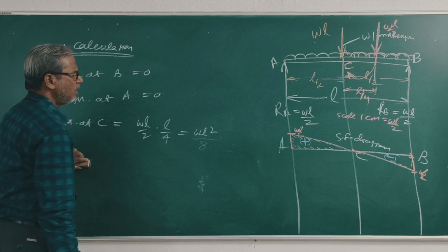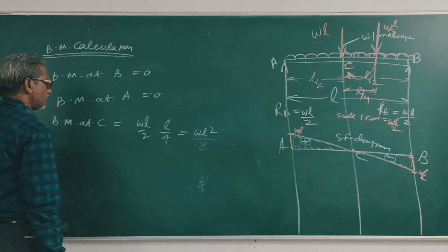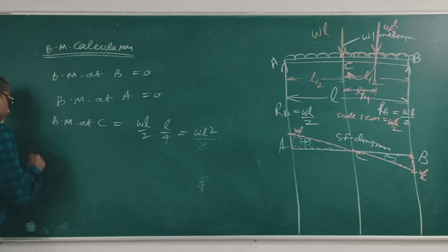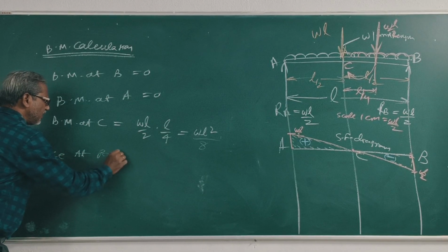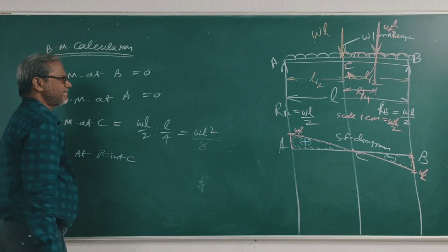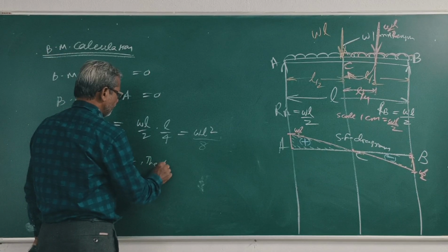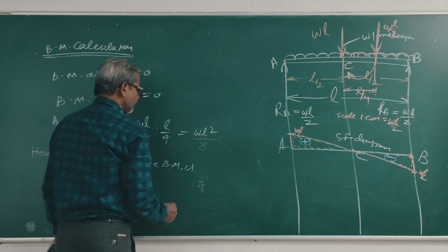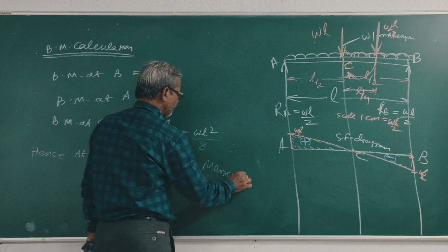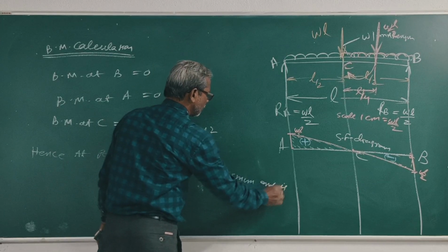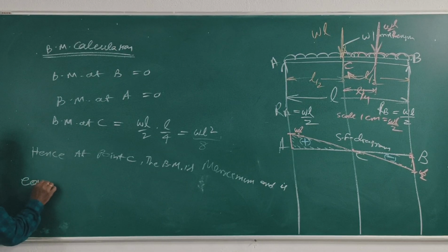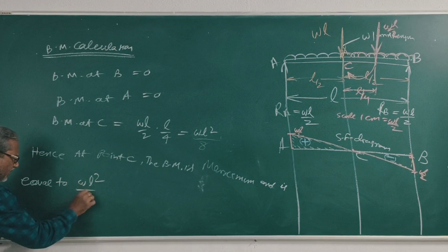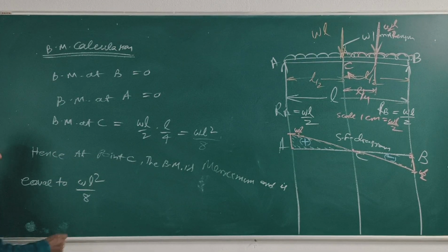Hence, at point C, the bending moment is maximum, and is equal to wL square by 8, where the shear force changes sign.